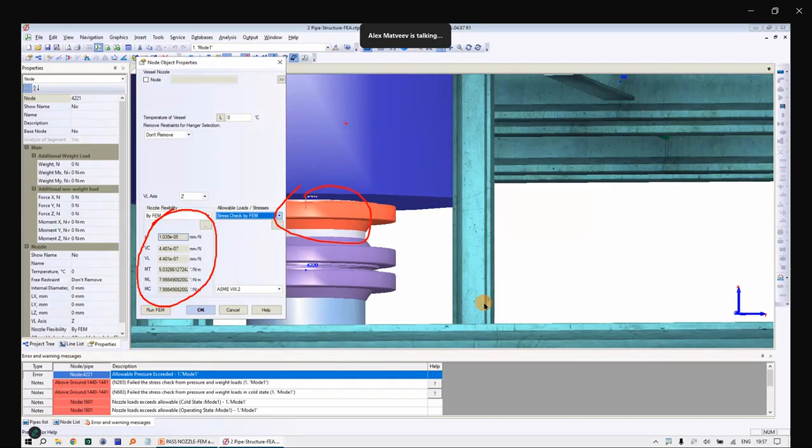After that, the pipe stress analysis will be performed, and after the pipe stress analysis, START-PROF will transfer the loads on this nozzle element and run Nozzle-FEM software to calculate stresses in this nozzle. So if you choose stress check by FEM, the Nozzle-FEM software will be run twice: first before the analysis of the pipe stress system, and the second time after the analysis.